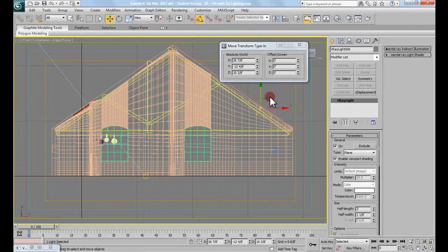And what I'm going to do is not create another light. I could create another light and do the same thing, make it a skylight portal. But again, I can't stress enough making instances of things, especially when it comes to more complex scenes. If you have your geometry instanced when you can, and your lights instanced when you can, you're going to save an incredible amount of time when you go to render it. When I hit that render button, your light cache calculations really shouldn't be taking more than a few minutes after you turn it up for your final production.